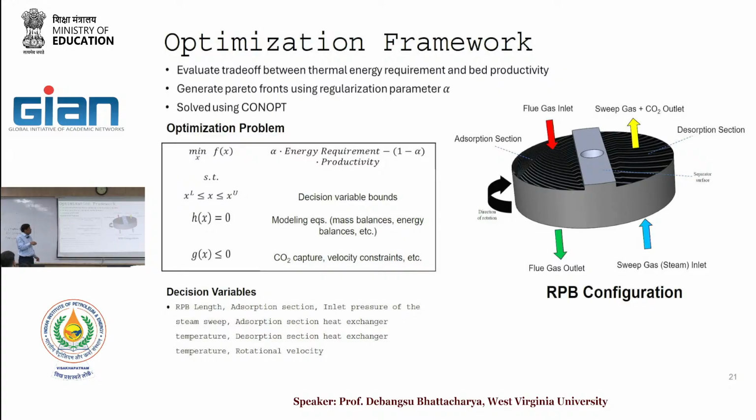So it is possible to do a non-uniform distribution. You can also consider a uniform distribution and all of those. But for CO2 capture, it is possible to have, because what does not show up here is that there is a distributor at the top of it. And that comes from the distribution systems there, how you like to design it. If you say the front portion should get more flow rate, the later portion not much, you can actually incorporate it that way.